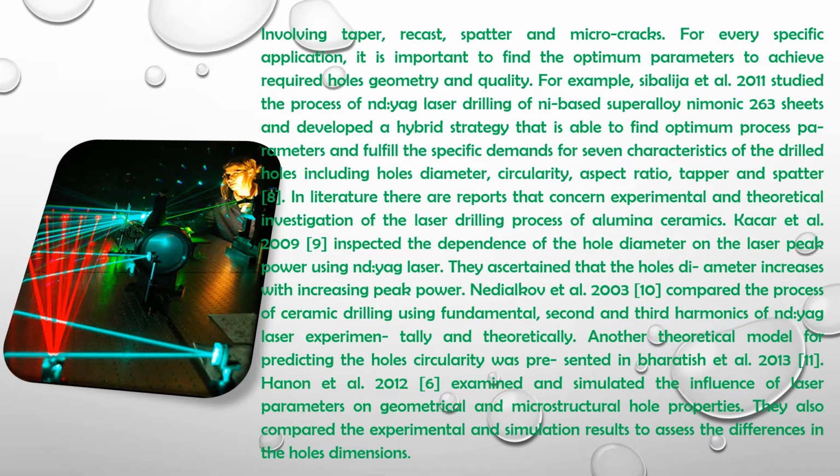In literature, there are reports that concern experimental and theoretical investigations of the laser drilling process of aluminum ceramics. Parker et al. 2009 inspected the dependence of the hole diameter on the laser peak power using Nd-YAG laser. They ascertained that the hole diameter increased with peak power.